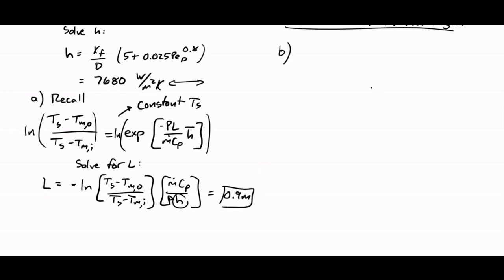So now we just need to do part B, which is what is the heat flux at x equals L into our fluid from the surface. We've already said about, let's rewrite it. The heat flux for internal flow at any point can be written like this, where we put in the mean temperature at our specific point and H at our specific point.